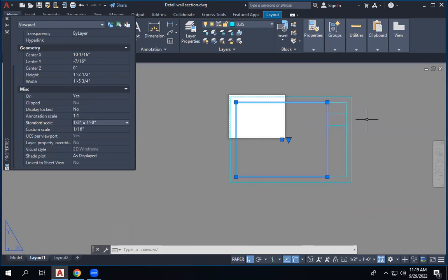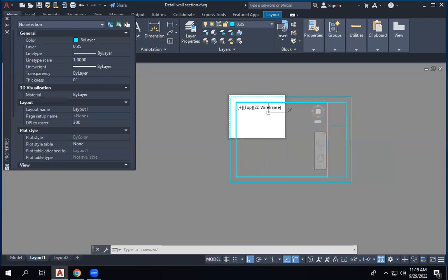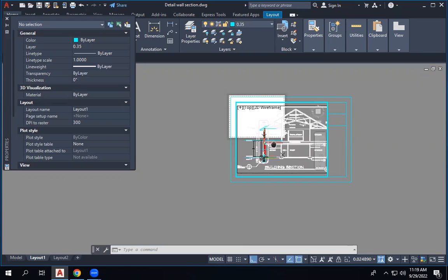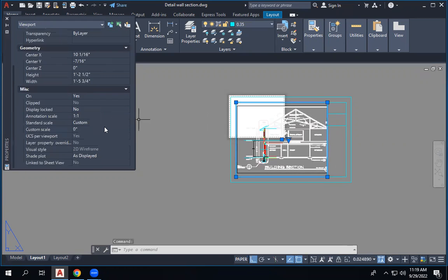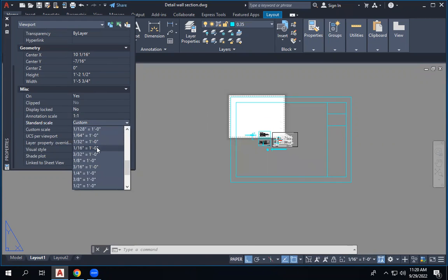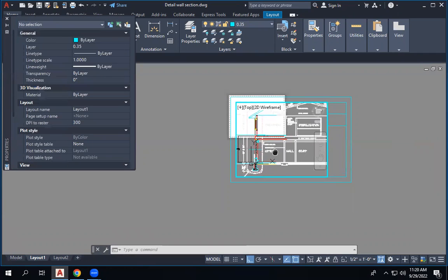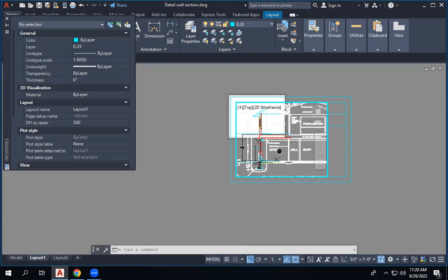And you go inside. First you need to, yeah, first take your drawing here, otherwise it will be messy. Yeah, you zoom it here and go outside and select the viewport and make the scale to 1.5 inch to, so this is the scale size.